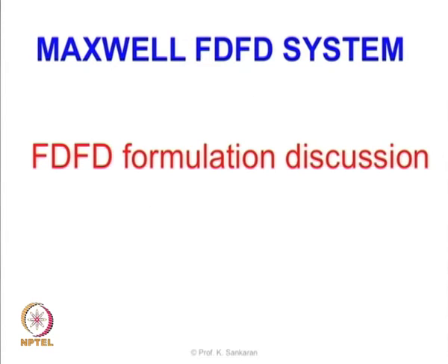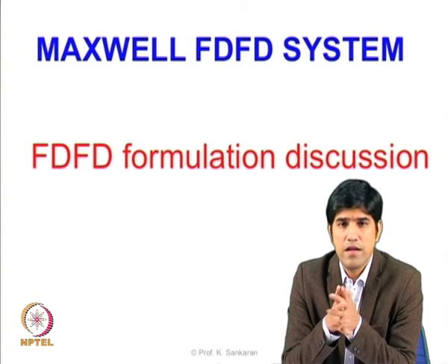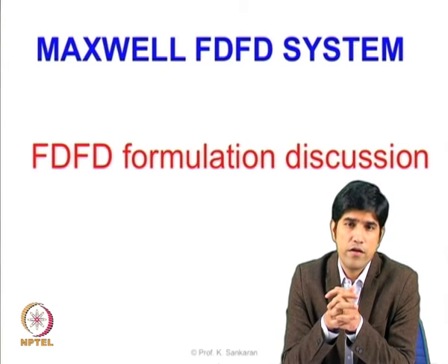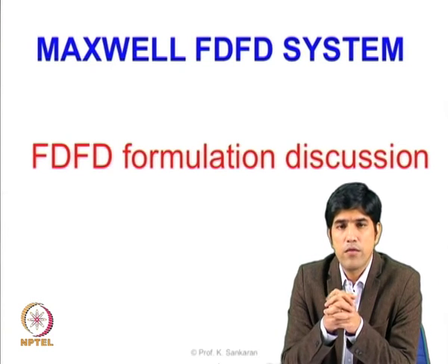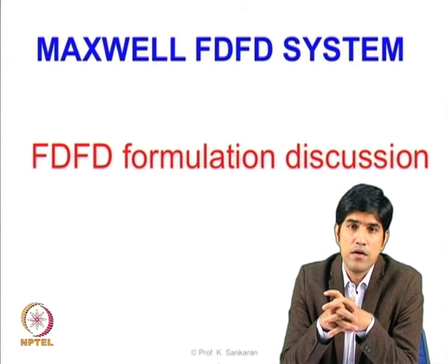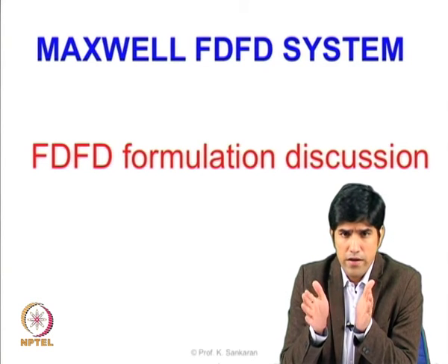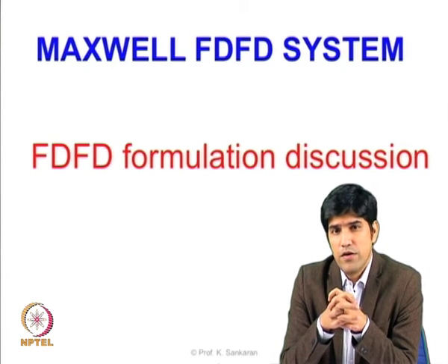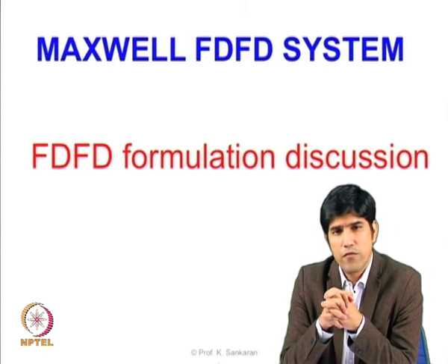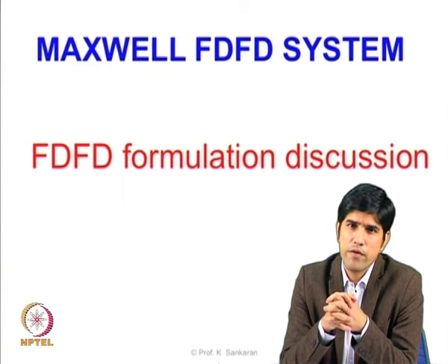So I said that we should have a word about the frequency domain simulation. What I wanted to say here is, when you are doing a frequency domain simulation, what you are interested in is a series of frequencies where you are interested in simulating your problem. It could be one frequency, it could be a group of frequencies. When the simulation itself is quite simple, your domain is quite simple, it is not a big issue. Whereas when you have a large simulation where the number of cells is going to be quite large, simulating it for individual frequencies is going to be very difficult.